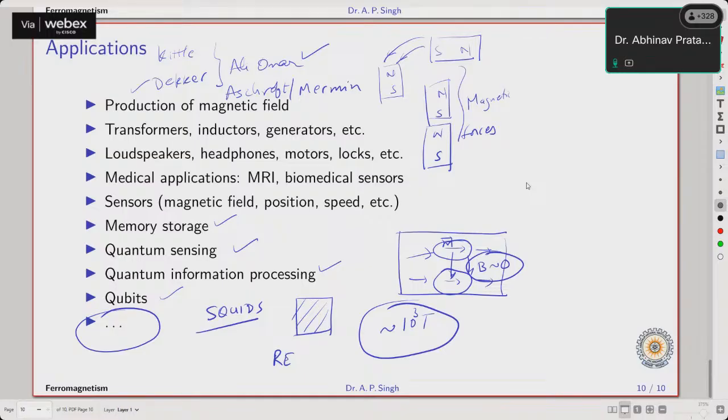That is why if you want to go towards 10 Tesla or more than 10 Tesla, then the cost becomes very, very high. Why? Because you have to use superconductors, you have to constantly cool them below their transition temperatures, and therefore it requires a lot of machinery and a lot of resources, and cost goes very, very high. But as I said before also, there is a limit till which alloys can produce the magnetic fields that you require.